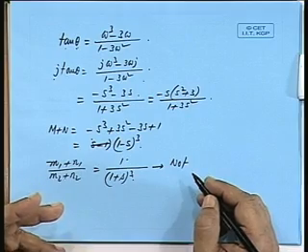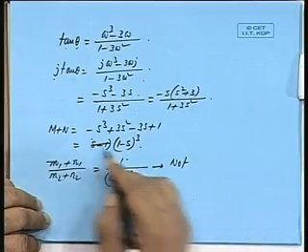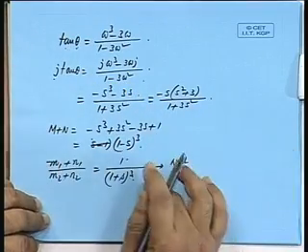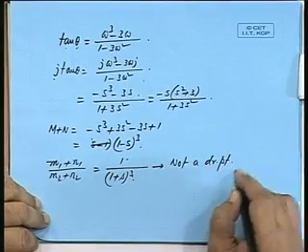A transfer function is a ratio between two voltages, say, or voltage and current. So, that transfer function can be anything. It can have only one condition, the poles must be in the left half plane. So, yes, this is any stable system. Any stable system may have a phase function like this, but this is not a driving point impedance or admittance function.